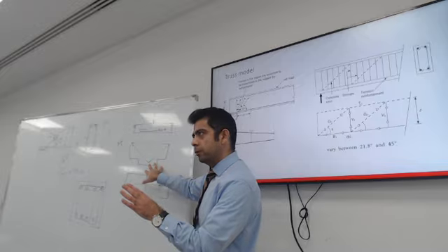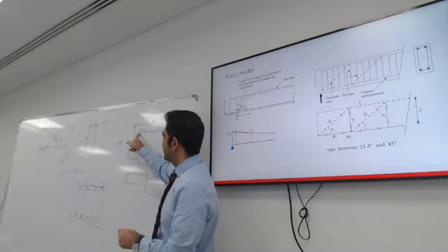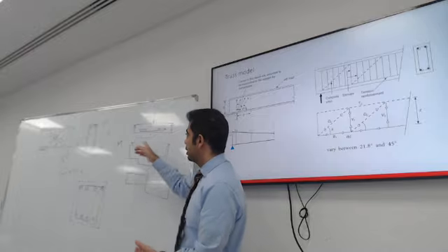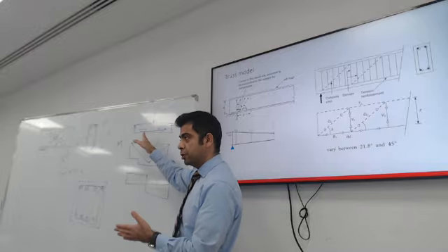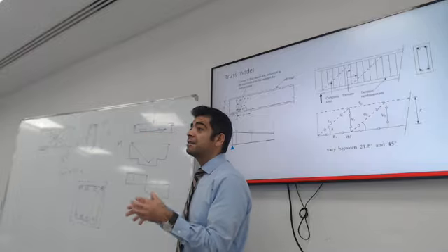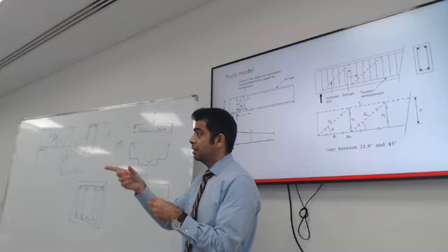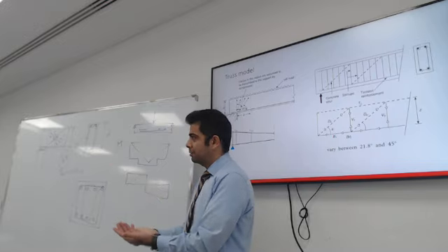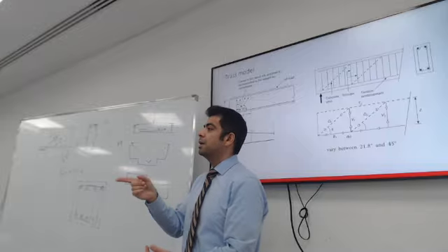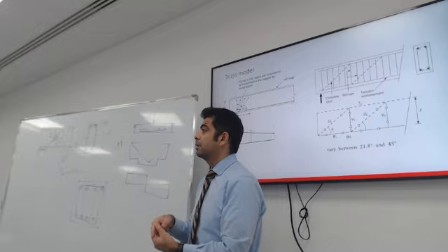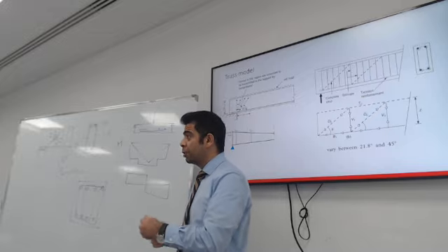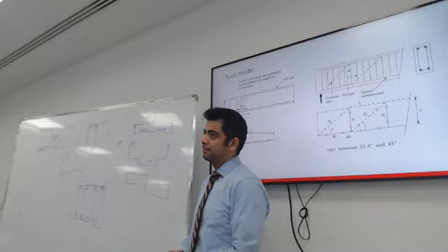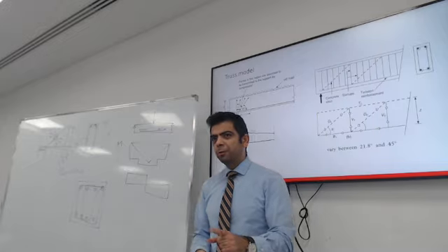So what we're going to do is extend the bar and calculate the additional force that goes into these bars and make sure that our section has enough area. Otherwise, you are right, I might need to add more bars based on the shear load. If you have very high shear force, I might need to increase the bottom reinforcement, which is counterintuitive.